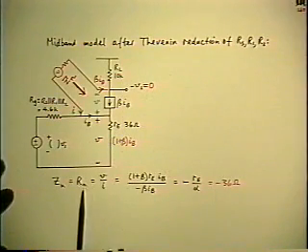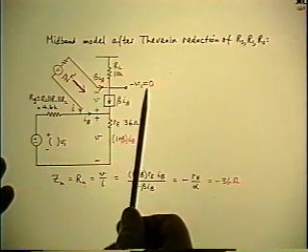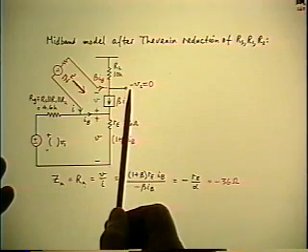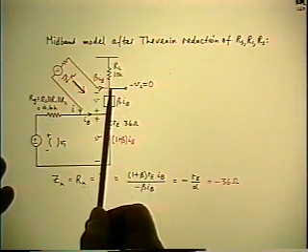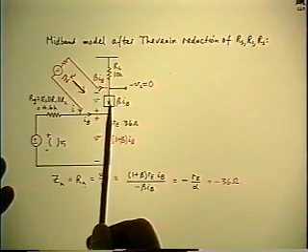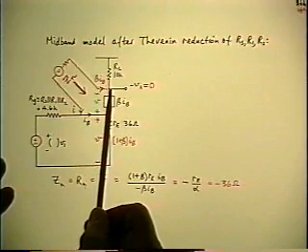Well, let's see why it is so easy to get this answer. You use the null, you propagate it back. So the first step of the argument is, if V2 is 0, there is 0 current in RL. Now previously that meant 0 collector current also, but it doesn't mean that this time, because there's another connection to this point.